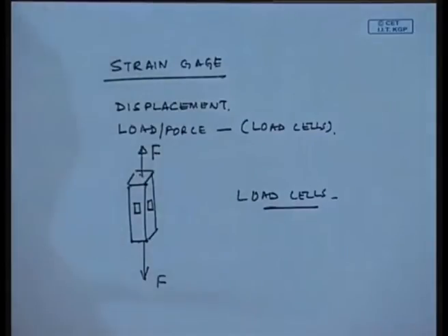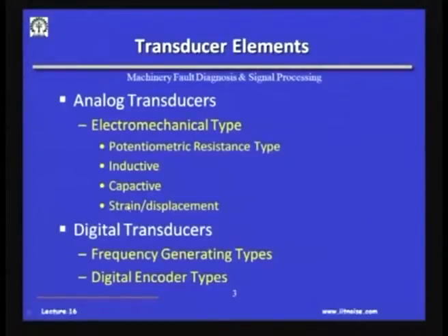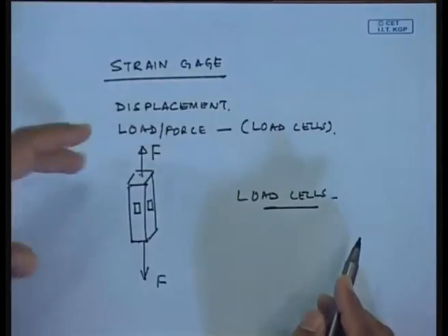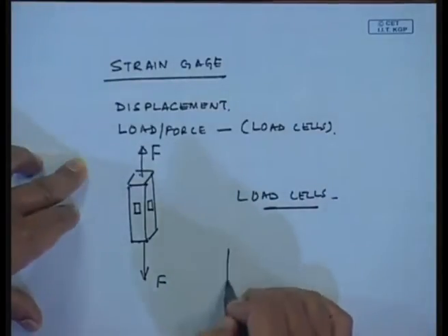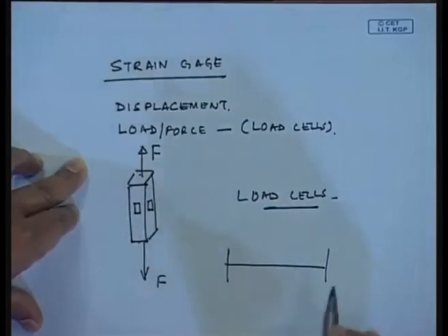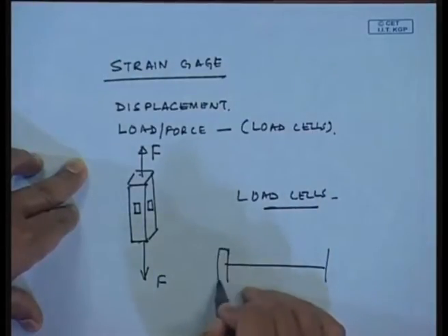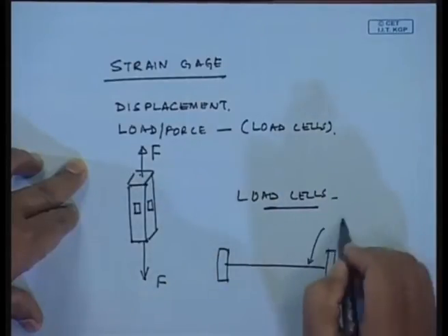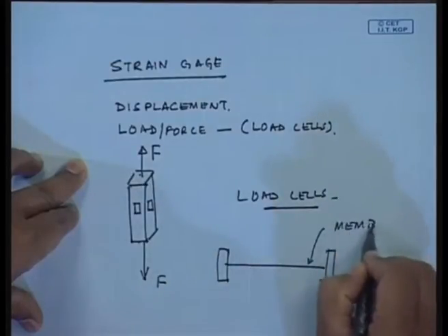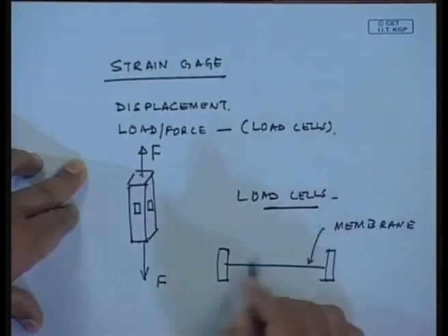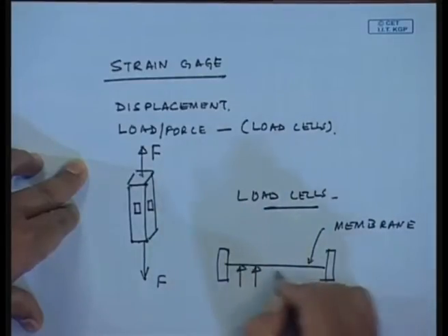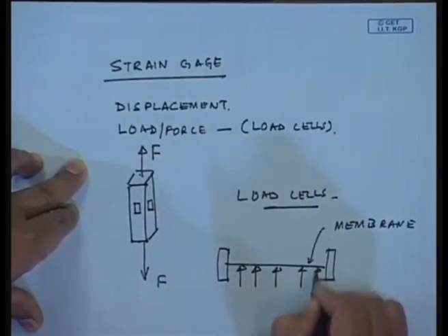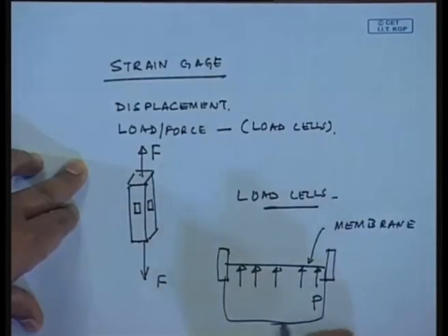So, an electrical resistance strain gauge is this sensing element, but the mechanical parameter could be load, could be displacement, could be pressure. For example, there are diaphragm types of pressure gauges, okay, and these are held in this thin membrane. And there is a certain pressure P here, and of course this is there in a housing, etc.